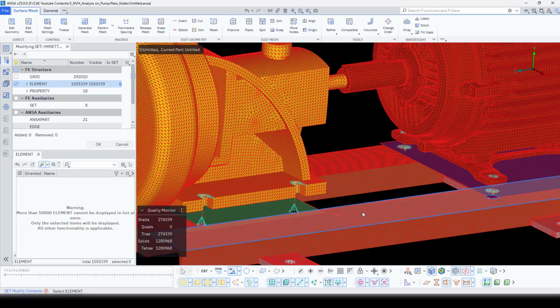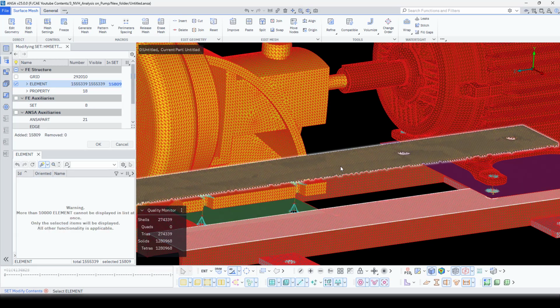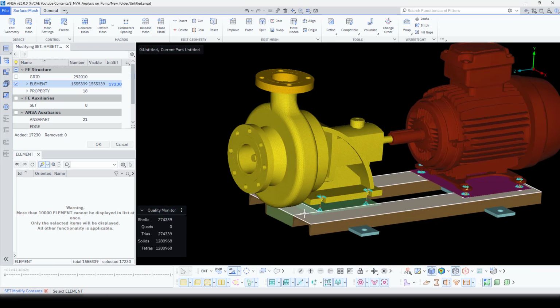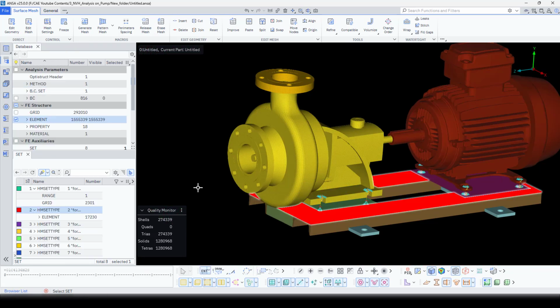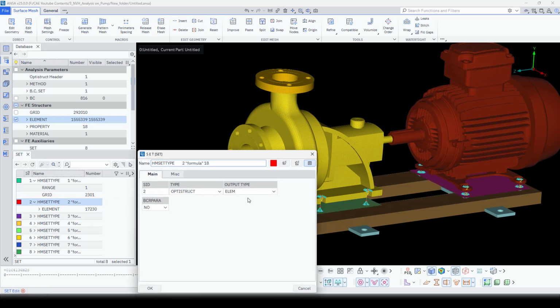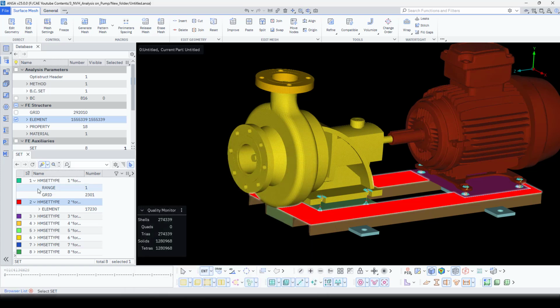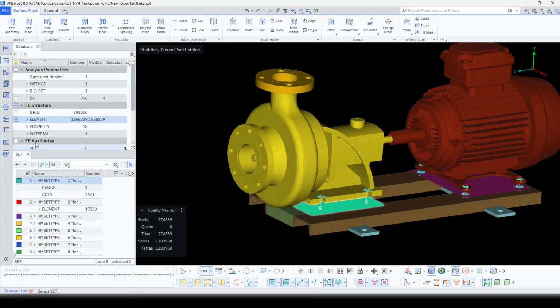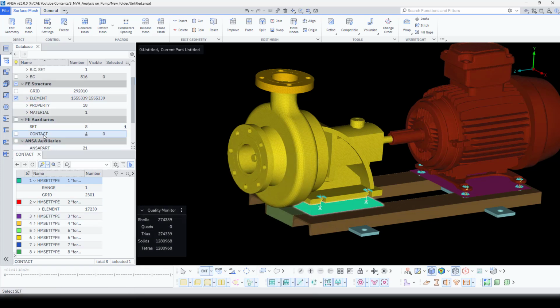Yeah, now you select the faces. As I told, you can select whole face instead of selecting the region only. Before I had selected the region itself, right? So likewise. Now middle click, you could see now it's all element sets. Correct? So why I'm doing this is, while defining the contact, you should have the node to surface contact for the tie.